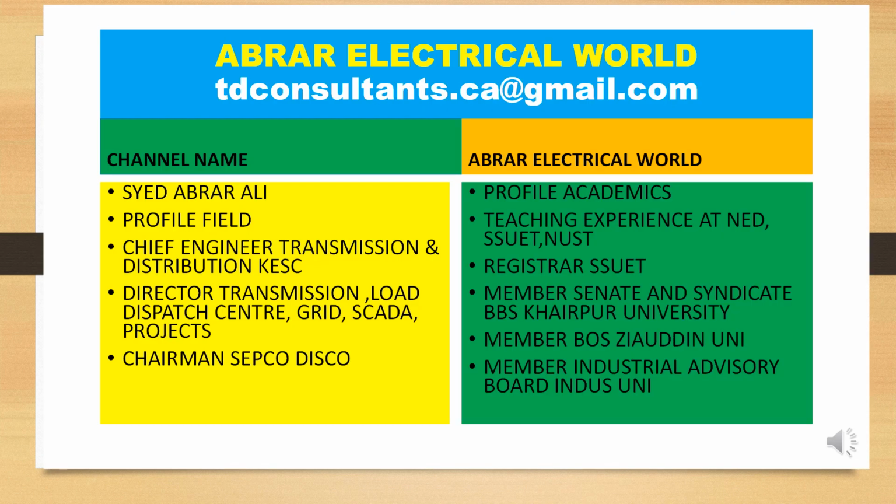So I hope I am able to explain to you the basic fundamentals of transmission line protection. And again to repeat, there are three types: impedance relay, the reactance relay, or the admittance or mho relay. And don't forget that the differential protection may also be used for small lines or short cables, and overcurrent and earth fault are also used as a backup for the distance relay.